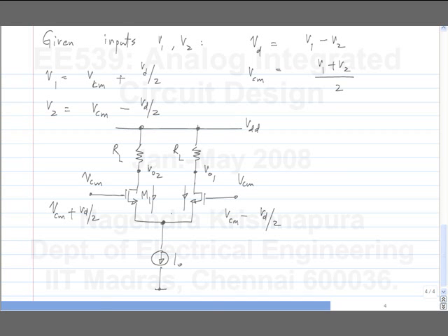As you increase VD, the source voltage is the same. The gate on the left side will go above the gate on the right side. So more current will flow through the left transistor. That will happen until all of the current flows through M1. Similarly, if VD becomes negative, more current will flow through the right hand side transistor, and if you go on increasing VD, at some point all of the current will flow through that transistor and it will stop there.